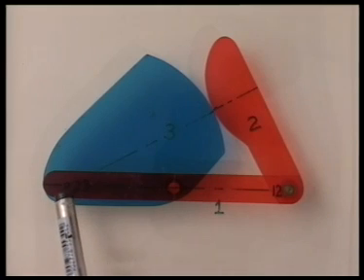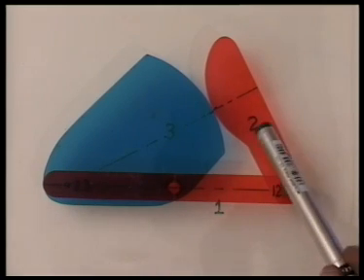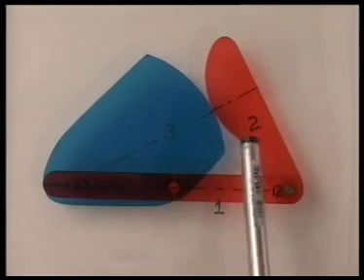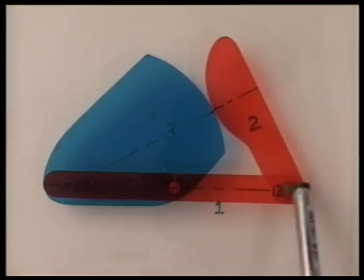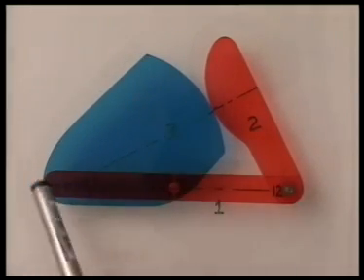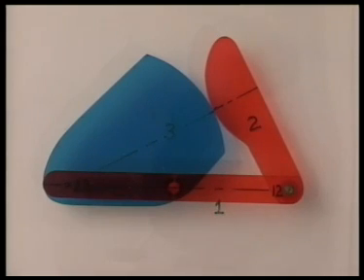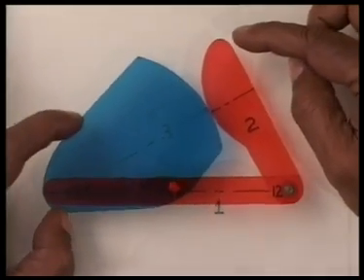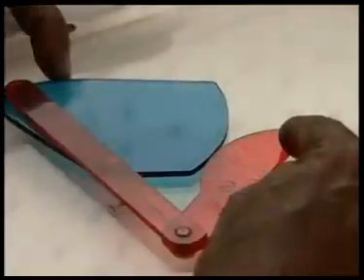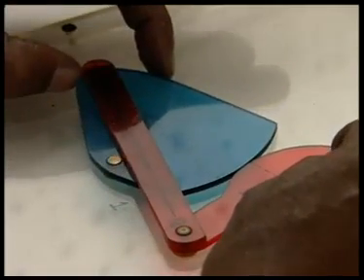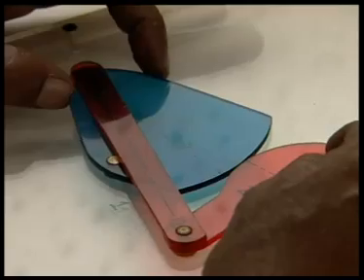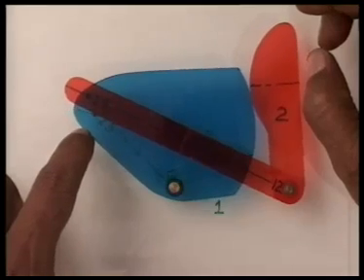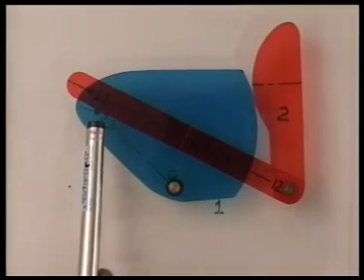So, this is the relative instantaneous center 2,3 between two moving bodies 2 and 3. By definition, at this instant, if I consider this point to be a point on body 2, that is this red link, or a point on body 3, that is this blue link, they have the same velocity. So, as we will notice, around this configuration, these 2 points on body 2 and body 3 at the location of I2,3 move with the same velocity.